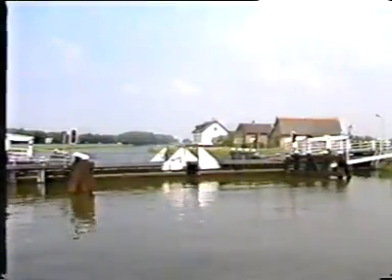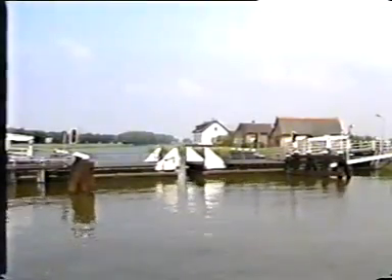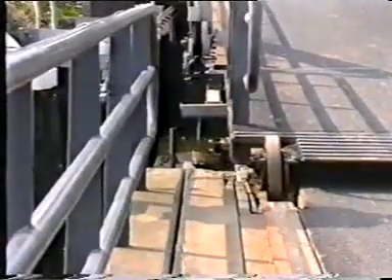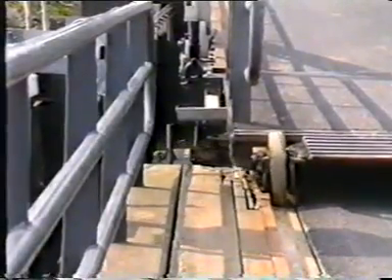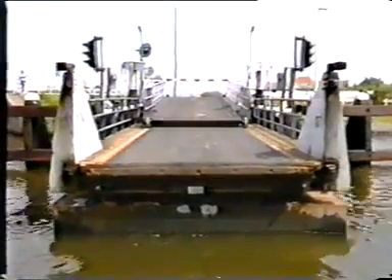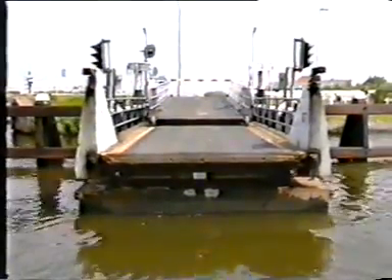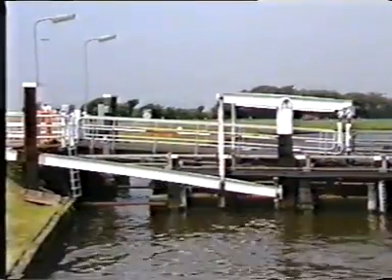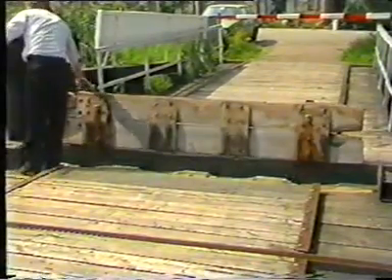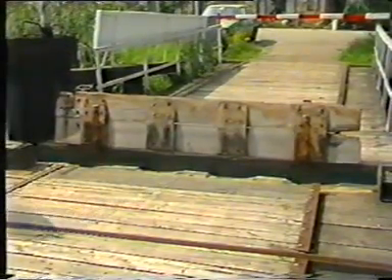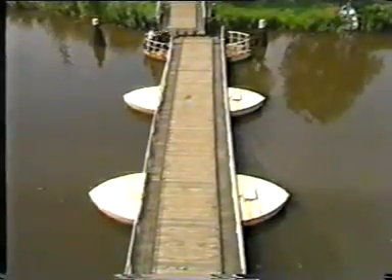A floating bridge is an alternative to make a passage. Here, pontoons fulfill the function of the bridge and support the deck. A system of cables pulls the pontoons under the approach spans to let the ships go through. A next step in the direction of a swing bridge is this pontoon bridge.